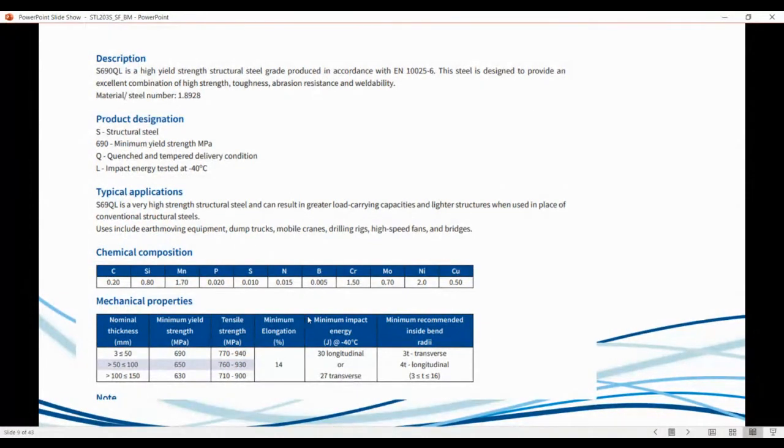So then you also get high strength structural steel. Of course, these are more expensive, and their minimum yield strength is 690. Can't even imagine. A tensile strength of 940. So I'm just letting you know, in comparison, a UTS of 940 is what you can expect from a high yield structural steel. Of course, these will be used if you need big load carrying capacity. You can kind of figure the general steel will probably do this, but in a high-end application, you'd probably use an S690QL steel.